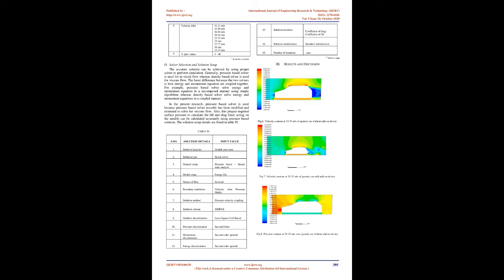On one side, simple flow over simple geometries, like laminar flow over a flat plate, can be solved analytically, but for complex flow like over a bluff body, the flow is turbulent and the Navier-Stokes and continuity equations can't be solved analytically. On the other side, it is impossible to get a direct solution for the Navier-Stokes equation with the latest computers available. In order to overcome this problem, a time-averaged Navier-Stokes equation is used, i.e.